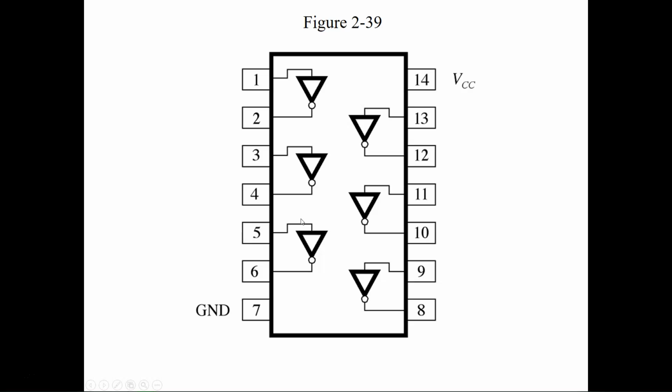So again, your 14 and your 7 are your what? What are 14 and 7, guys? Is there a relay? Nope, 14 right here is your voltage in, 7 is your ground. So this guy can't be electrically active on his own. He's actually got to be hooked up to be able to run the chip.